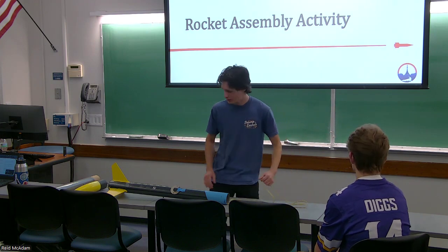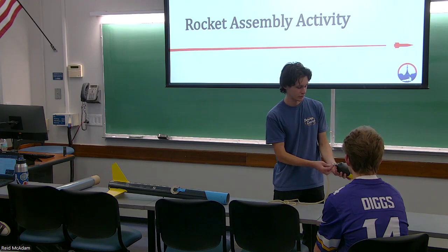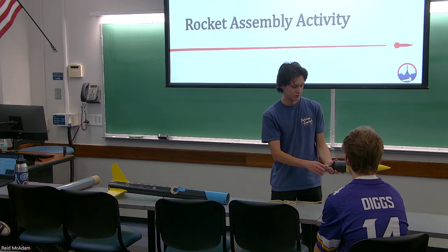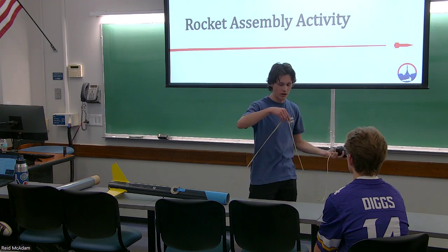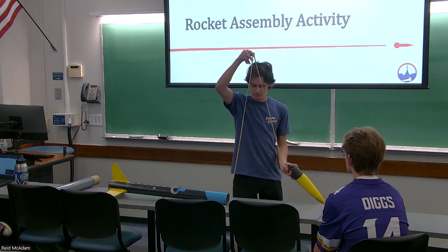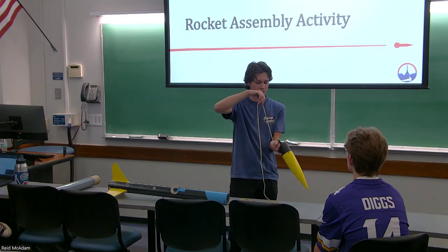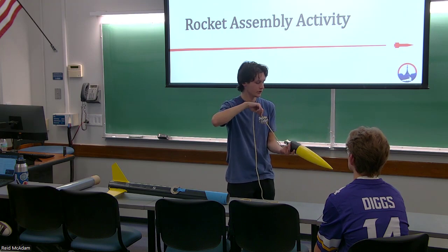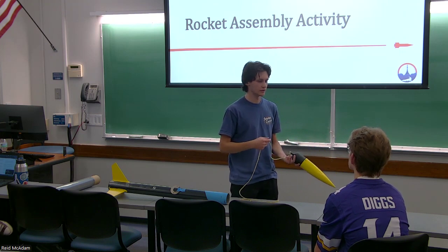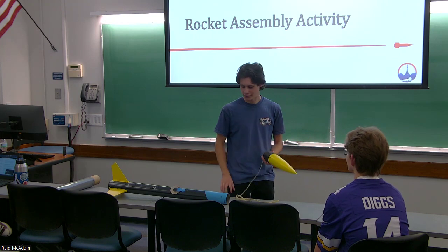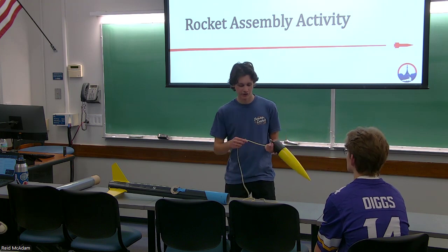So this is my shock cord. Usually the other end of this would tie through the eye bolt here, so that when it's separated, they're both underneath the parachute, which would usually be right here, pretty close to the nose cone. It keeps both sections connected so that I didn't have to look through the woods, but also keeps enough distance that the two sections won't collide.